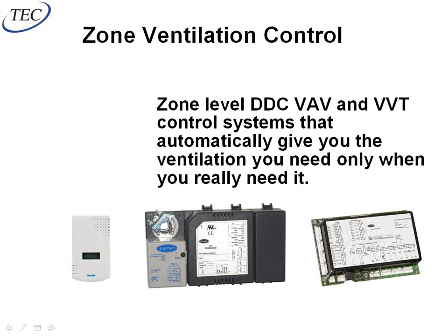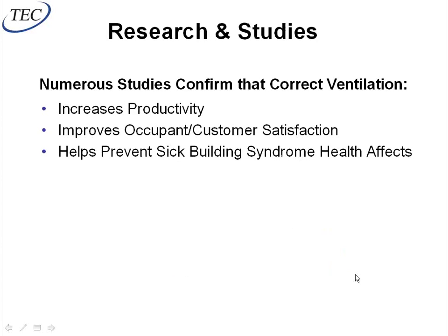So that'll either be an air handler controller, a rooftop controller, and if you don't have a DDC system, it might just be the economizer itself. It might be able to take a CO2 signal in. And if you have a zoning system, then your VAV controller is going to have the ability to handle this as well. Each CO2 sensor will wire to the VAV box controller, and those will all be talking to the air handler controller. And we'll go through an example of how that works here in a minute.